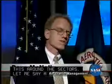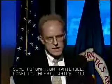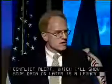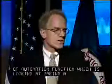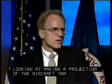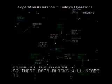Conflict alert, which I'll show some data on later, is a legacy automation function that makes a projection of the aircraft trajectory based on 2 or 3 track hits. So if any of those aircraft are predicted to lose separation within 2 or 3 minutes, those data blocks will start flashing, alerting the controller to the potential problem.